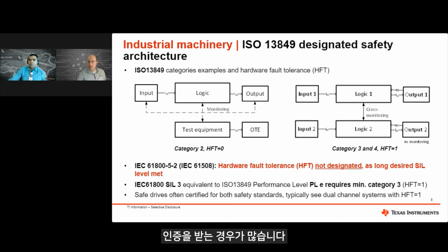Let's see a few examples here where FMEDA customization is required by the end user. First, a change in the technical safety requirement or safety concept at the application level. The microcontroller is considered to be designed as a safety element out of context, that is SEooC, and these component FMEDAs are created based on assumptions of functional safety requirements. Hardware safety requirements at the microcontroller level for each part and subpart are satisfied by implementing safety mechanisms that are described in the safety manual. This will meet the allocated safety integrity level for the microcontroller.